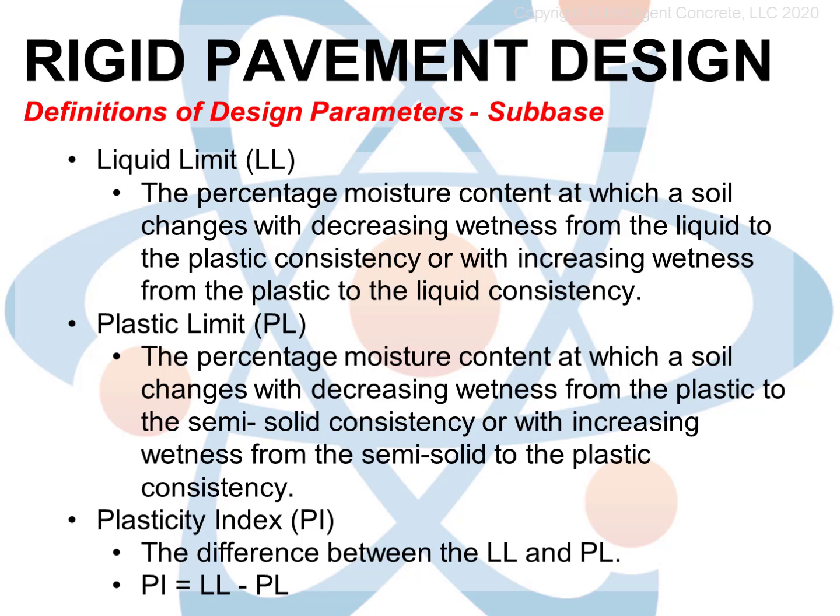Whereas if a soil has a greater percentage of silt and clay with little sand to carry the load under high soil moisture contents, a much lower PI would be required. Again, don't fret too much about how all this works. Soil mechanics at the most basic level is a semester-long class. Here today, just remember that a low PI is good and a high PI is not good. Any PI above 20 should be evaluated on a case-by-case basis by a soil engineer relative to the specific project.